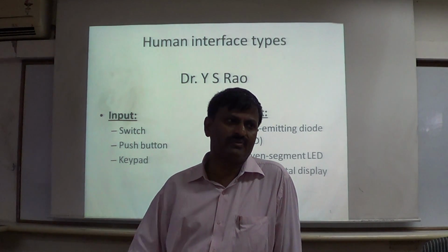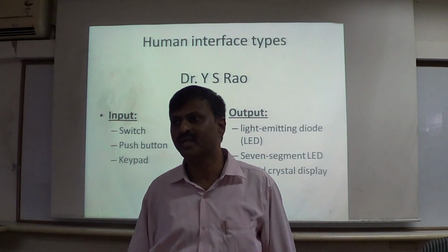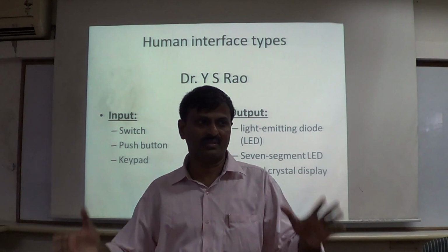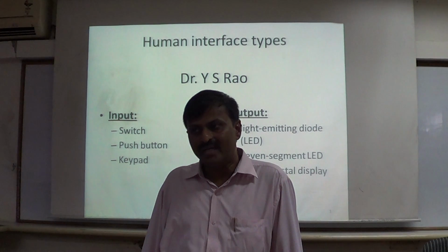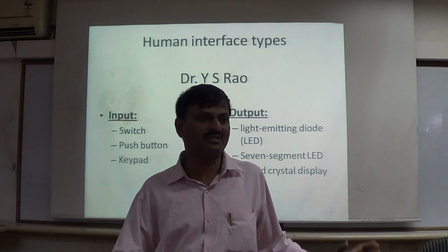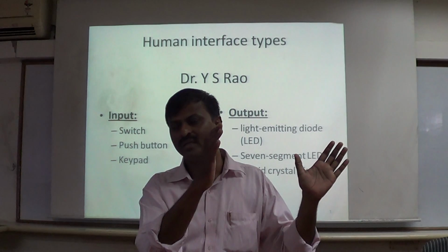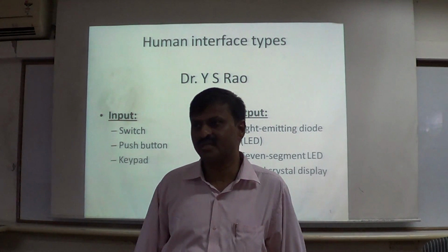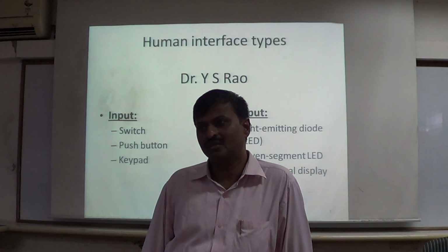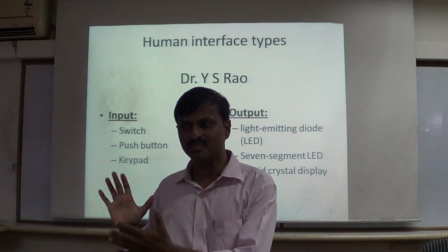But as we know, even for PV panels, we use tracking from east-west. There are 2 types of tracking on the rooftops: daily tracking and seasonal tracking. When it comes to daily tracking, it is east-west. Early morning around 6 to 7 it will be on the east side, then slowly it will move to the west side. East-west is every 4 minutes, 1 degree is the displacement.